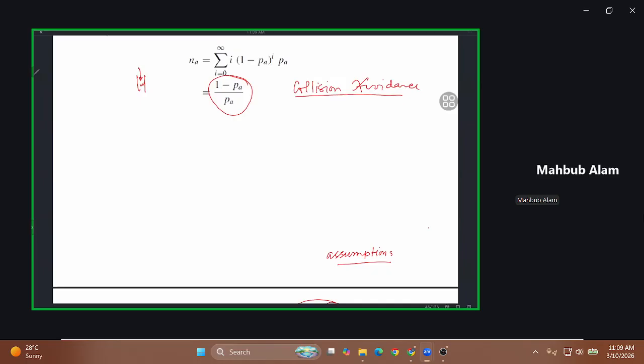This amount of time is required for assessing whether the channel is free or not. The station is in the receiving state and checks that the channel is free. If the channel is free and it has a frame, it starts the transmission. To start the transmission, it needs to change the transceiver from receiving mode to transmitting mode. So we call it a slot.